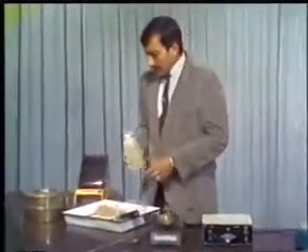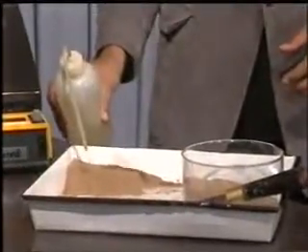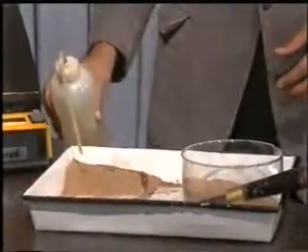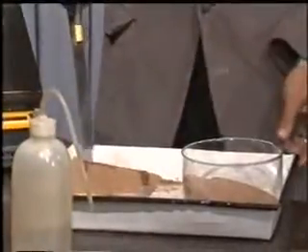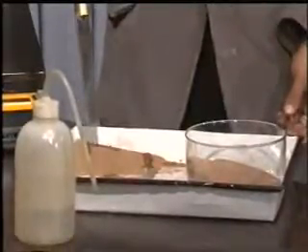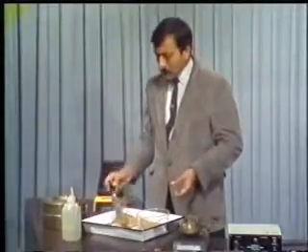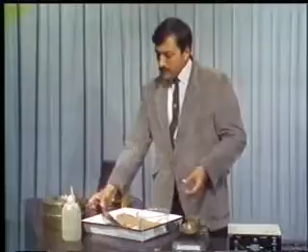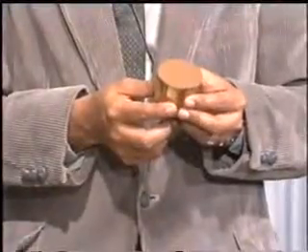The sample is prepared by adding some water and mixing the soil with water thoroughly so that a paste of uniform consistency is obtained. This paste is then transferred into the cylindrical container made of brass.